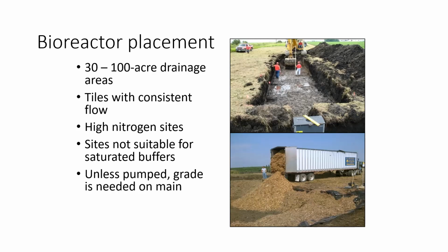If there isn't grade, there are starting to be pumped bioreactors now, which is interesting. There's actually studies to show that if you wet and dry bioreactors, you can kind of supercharge their effectiveness because you make more carbon available to those microbes that utilize that wood chip as their food source. And then, of course, once that wood chip is saturated and the whole condition down there is saturated, they start utilizing nitrate for their metabolism.